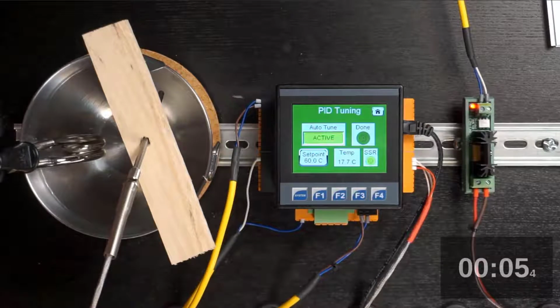What we are executing here is a Ziegler-Nichols tuning experiment being automatically run by the OCS. The OCS will run the process to the set point and actually a few degrees above the set point. Then it will drop it back down a few degrees below the set point, and it will do that 3 times.